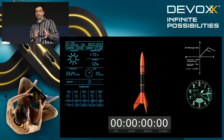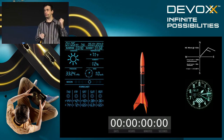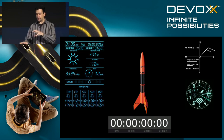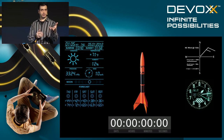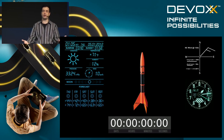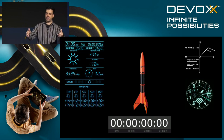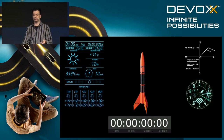And then there are several abort cases that we have to deal with. First and foremost, we need a manual abort button. So if something were to go wrong after our rocket is armed, we need to abort to exit that state. We're also going to use our key switch, and if we turn the safety off, that would also abort the rocket launch. And then finally, if someone approaches the launch platform, maybe we want to automatically abort the system because it becomes an unsafe environment if someone approaches the launch vehicle. So we're going to use our IR beam sensor here on the top of the demo board, and if someone were to cross that path, it's going to automatically abort our launch.